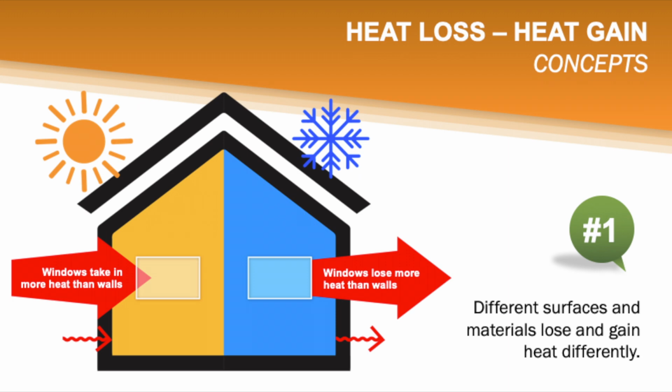Interesting fact, if a ceiling has an occupied space above, for example, another conditioned room in the house, or even another apartment, there is no heat loss or heat gain to calculate.